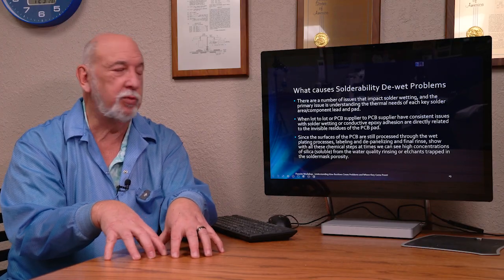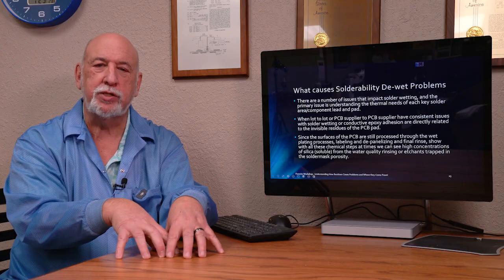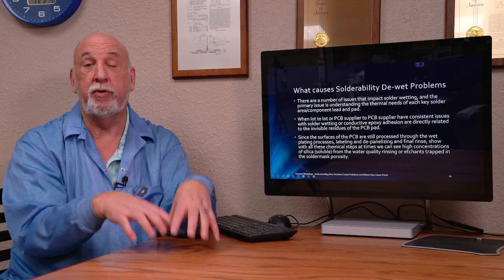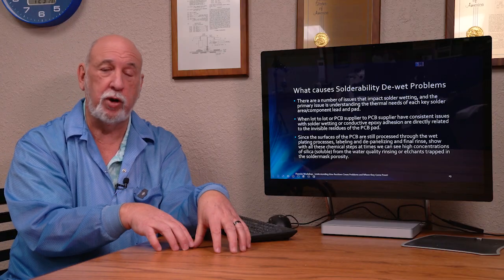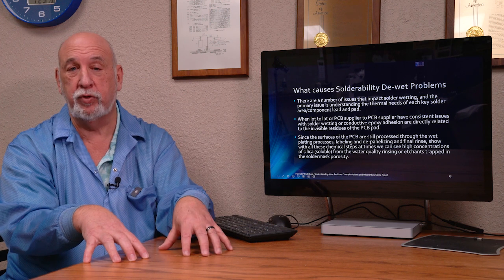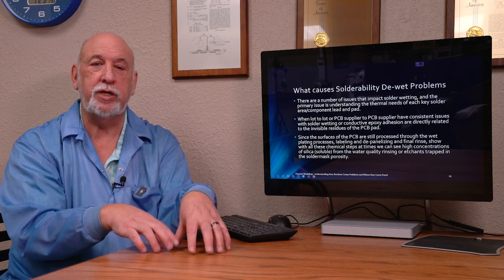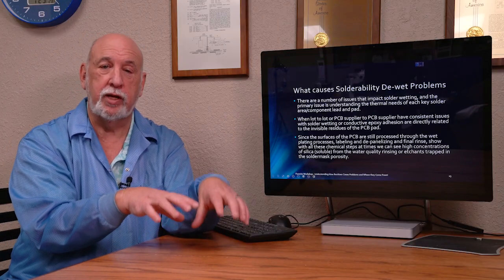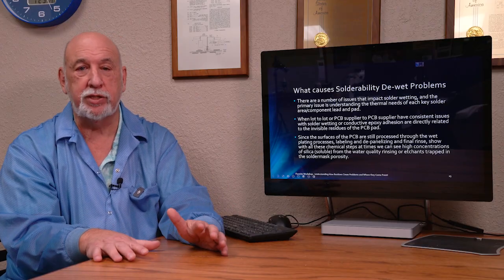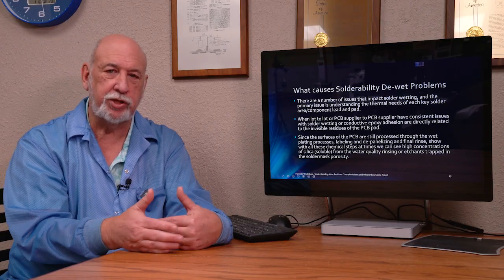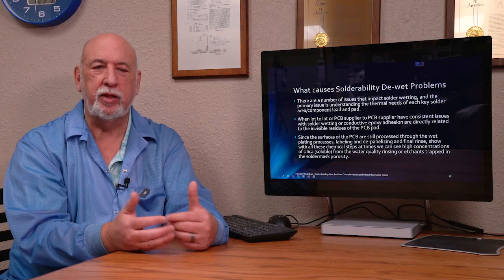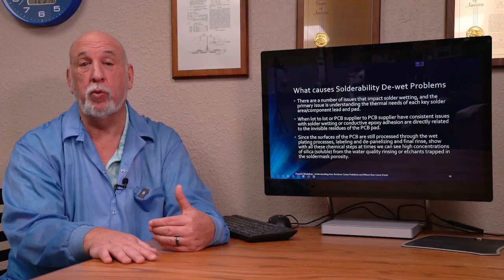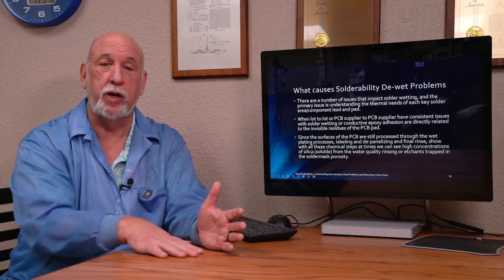We get a lot of solderable, solder de-wetting issues, and in many cases we find that those residues that are impacting the solderability come from the fabrication process, both in the component and at the board level. One of the key variables is soluble silica in the tap water depositing on the fresh metallized plated areas. And you won't be able to easily see these. Sometimes you'll see discoloration or slight hazing in the area, but the amount of soluble silica is a very thin amount,